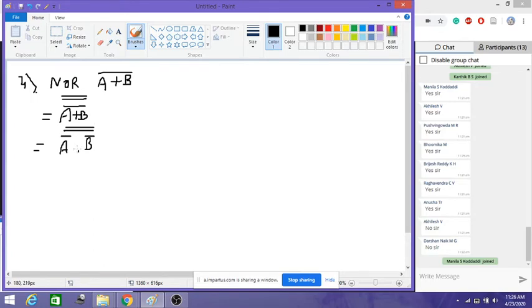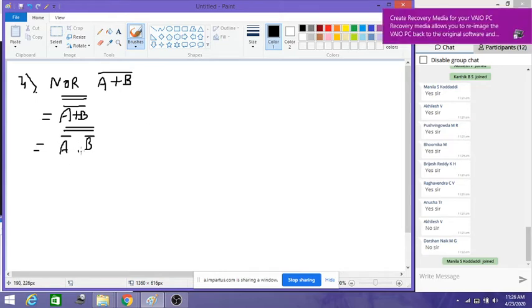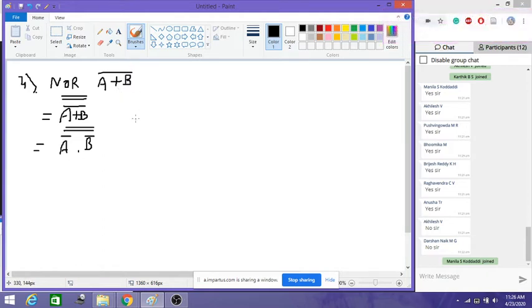Now it is perfectly in a NAND gate form. Let us keep it as it is. Now realize this; it should be in this form. Don't simplify this further. If you simplify further, you will not get anything; ultimately you'll get back the same equation. Now let us take the two inputs, A and B here.